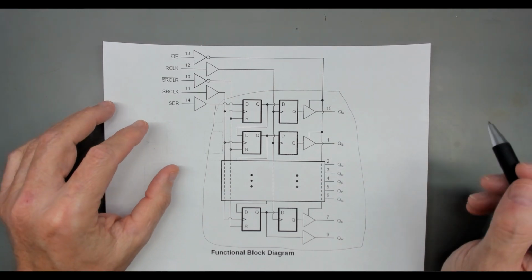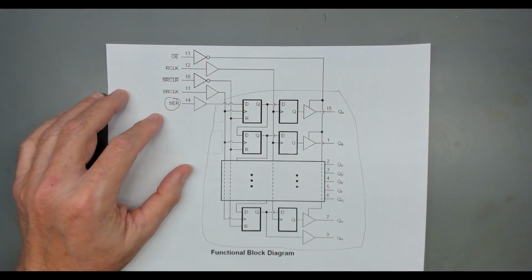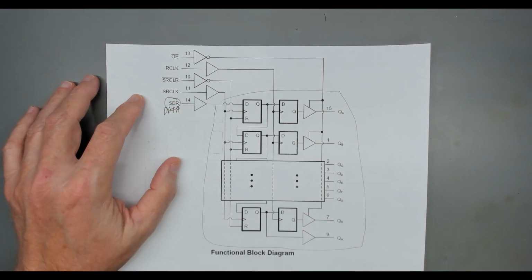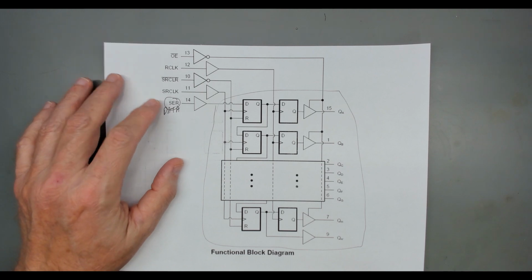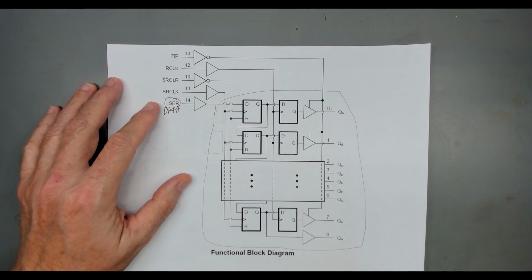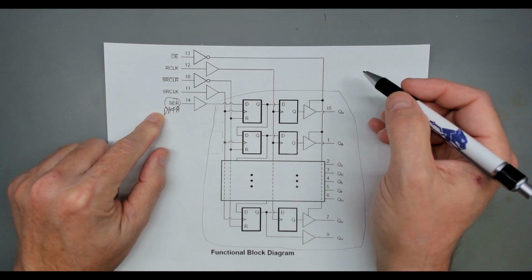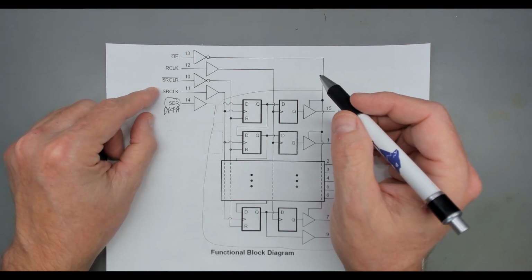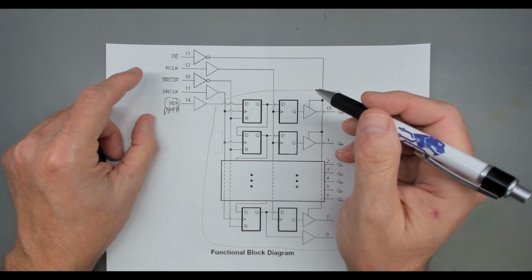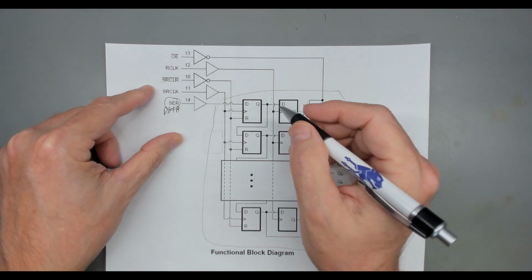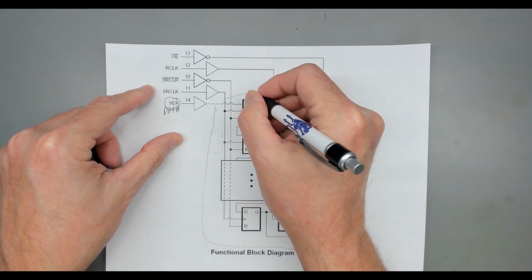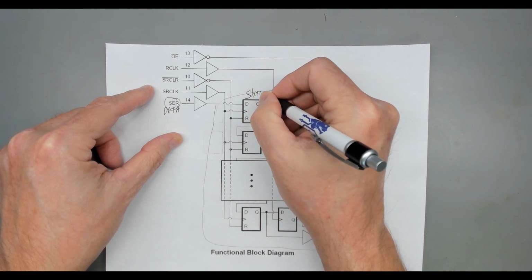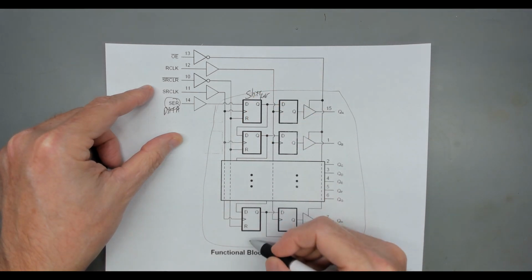And what happens is this line right here, SER, serial, I would say think of it, to simplify it, as data. I never like that they call it serial. Many logic chips will call that the data line. This is your data line. Then you have an SR clock. That is your shift register clock line. What does that mean? Well, this column here is your shift register.